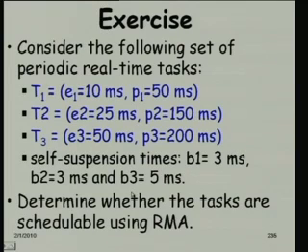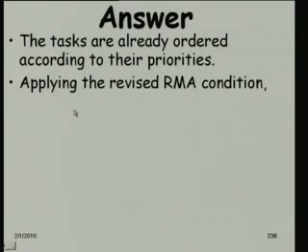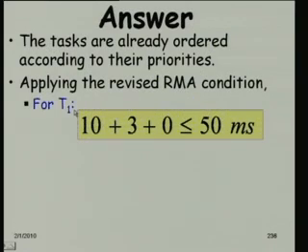So, will these tasks be schedulable? What do we have to do here? Calculate Bti for each and every task and then add it to each. Exactly. So, we need to compute the Bti for every task Ti, and then in the completion time theorem we need to factor in that delay. So, that is what is done here.